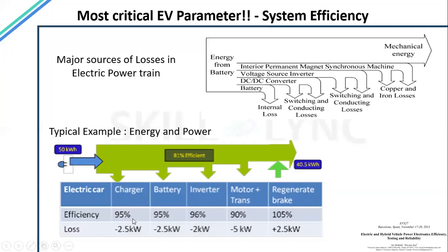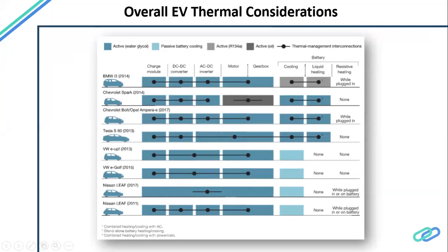And you can see the efficiency, overall efficiency around 80%, typically 79, 75. These are some ranges that you can see at particular drive cycles that they can give us. So these are the different thermal topologies being considered, because thermal poses a bottleneck in terms of getting more efficiency or driving the inverter and the machine at some particular point where it has a sweet spot.